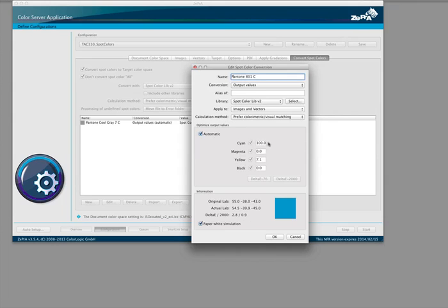If we want to look at why ZePrA prefers these values, you can go there and use again the delta E 2000 functionality. And what you're seeing is that it is not perfectly using 100% cyan normally. It prefers a little bit of magenta in here, but 2.2% of magenta is something you typically want to avoid in printing.